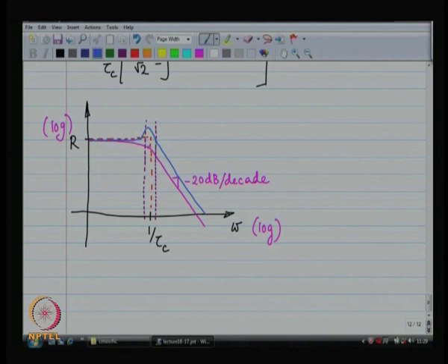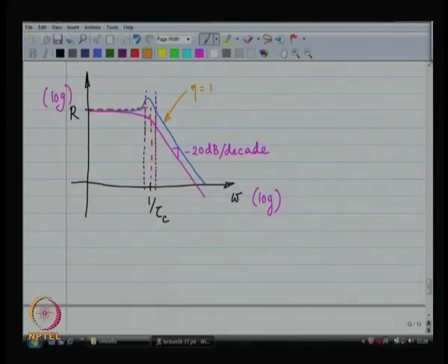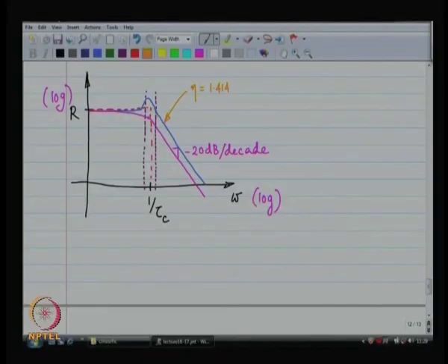So, this is the complete story. This is how the transfer function is going to look. Now, do you want this kind of a transfer function? The answer is maybe, but not really. I want a flat passband. So, my 3 dB frequency has increased substantially. I agree, this is probably my new 3 dB frequency, which has dramatically improved. Okay, but I like a flat passband.